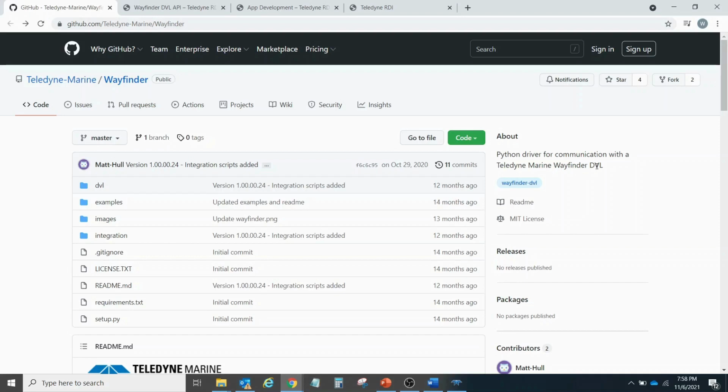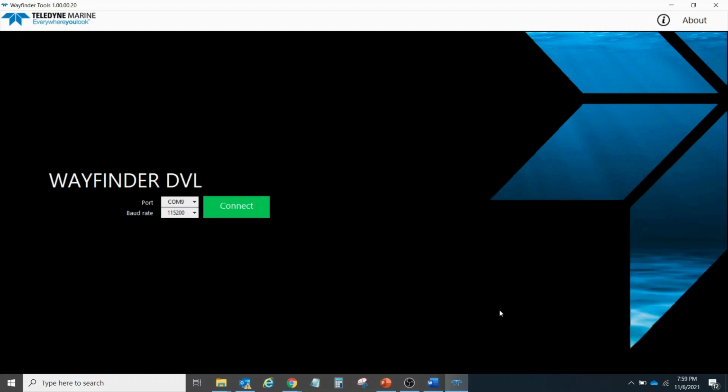That being said, in this video, I would like to show you how you can take advantage of Wayfinder Tools to make your job a little easier. This is the Wayfinder Tools software. So what I'm trying to do here is establish serial communications with the Wayfinder DVL using Wayfinder Tools software. To establish communications, it's pretty self-explanatory. You specify the port number as well as the baud rate, which by default is 115,200, and you hit connect.